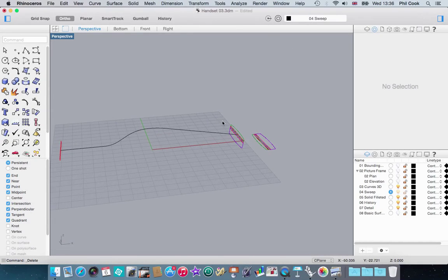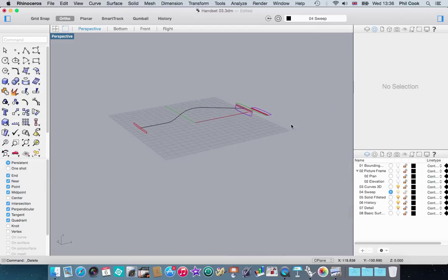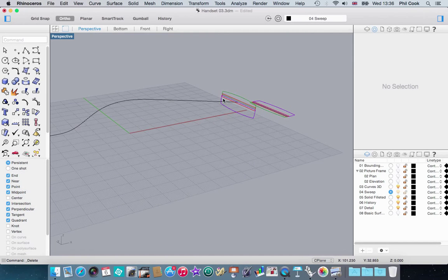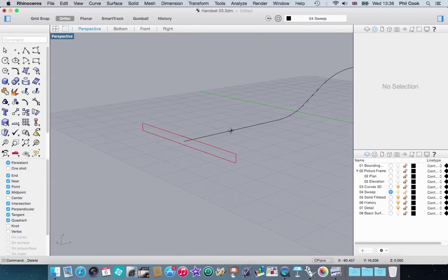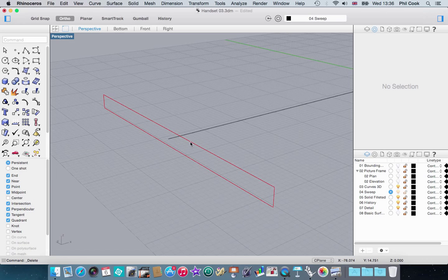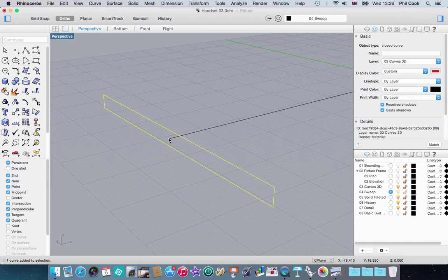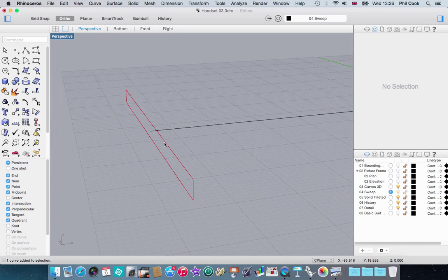Okay, now the red sections here represent the lip in, for example, the bottom moulding that locates the bottom moulding into the top, and the lip is set inwards from the outermost boundary of the lower moulding by a small distance, let's say 0.4 of a millimeter. So what I need to do is to actually move this red cross section along the rail or inwards on the rail by that distance.